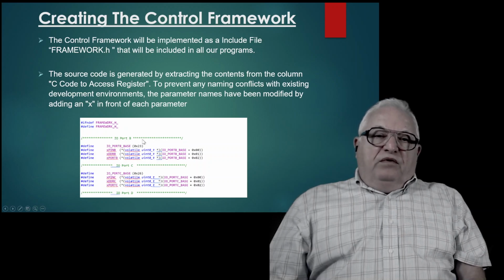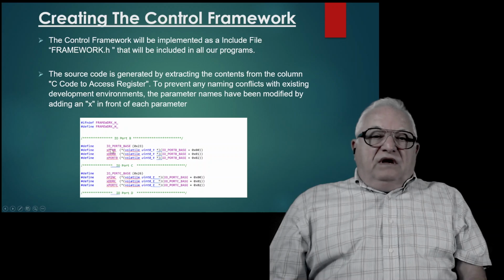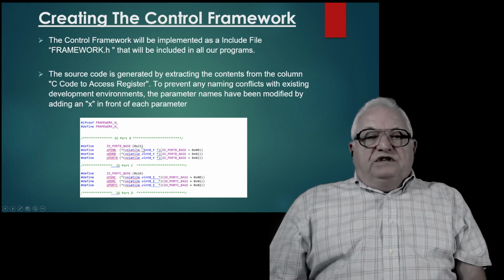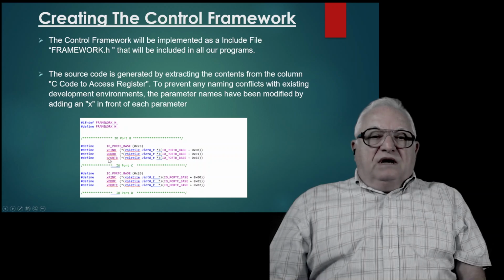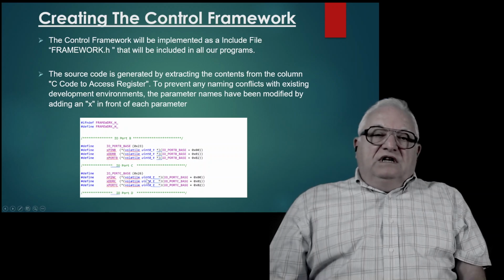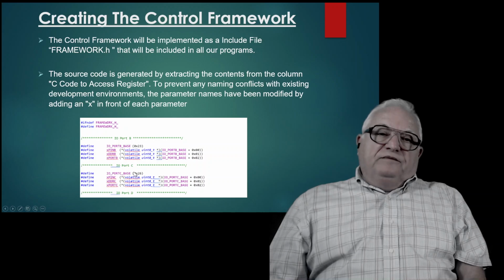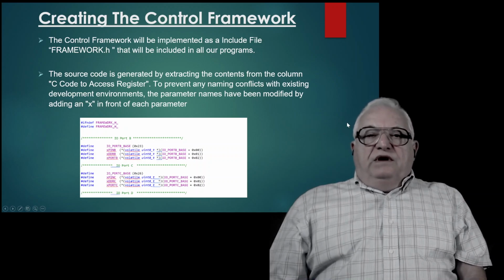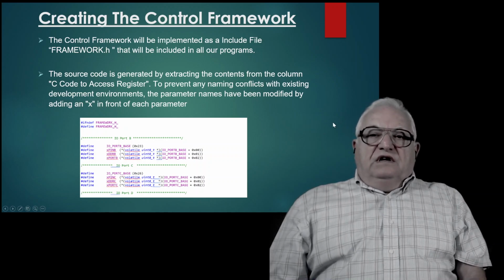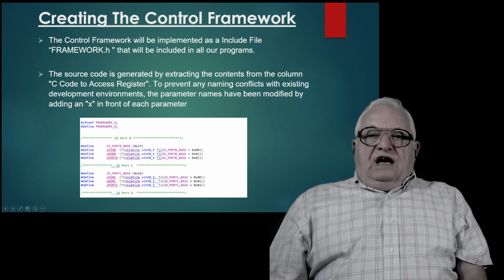So we have IO port B, and then we have the IO port base, which is hex 23, like I noted. And then pin B, they had pin B only, but I added an X on the back. And then I have here 0 plus 1 plus 2. Then I go to IO port C. So now let's go to an exercise which shows you exactly how I did this using the Atmel Studio.